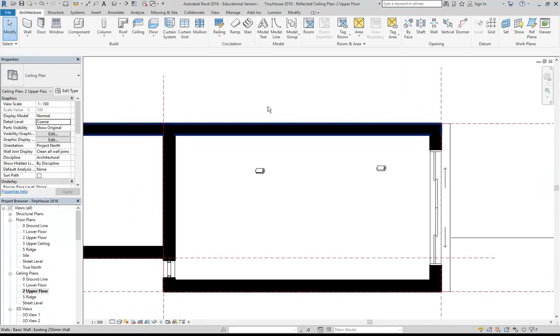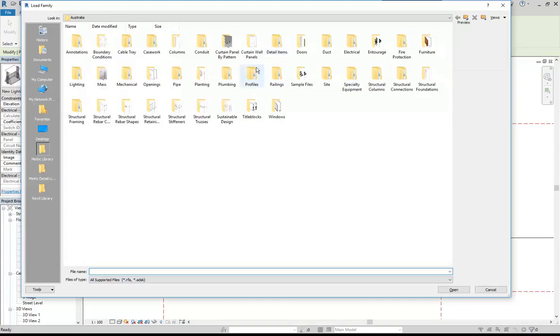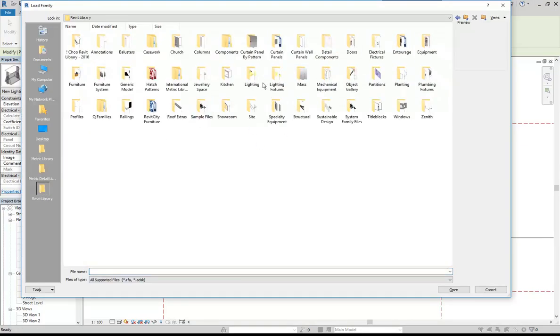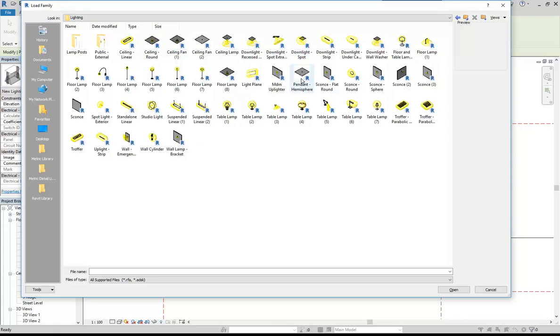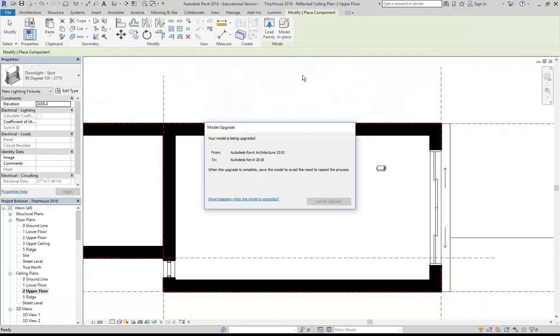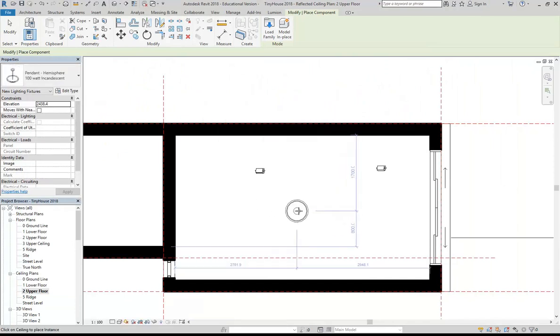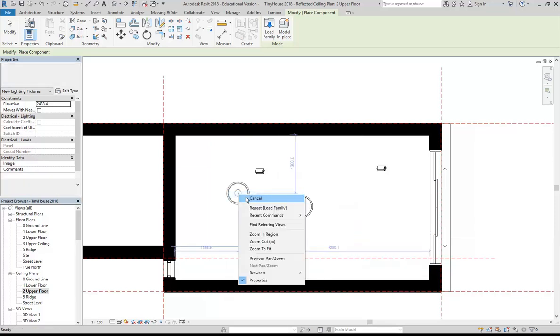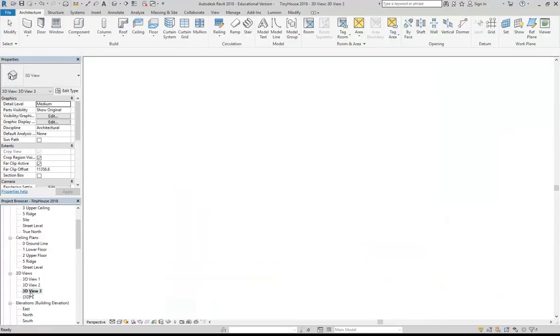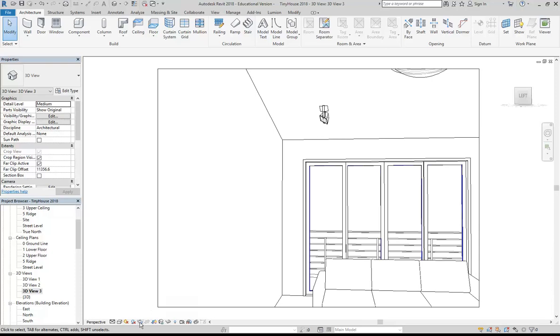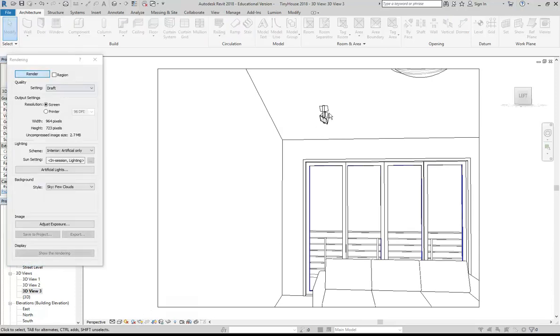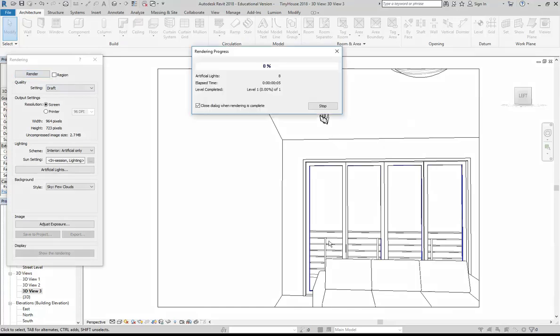So here, again, I'll go to the Revit library on the P drive and get maybe some basic pendant lights that are going to give me a bit more diffuse light generally through the space. Have to play with that, but I'll put one in now so you can see the difference. So as well as getting the targeted light now, I should get some more uniform light throughout the rest of the space.